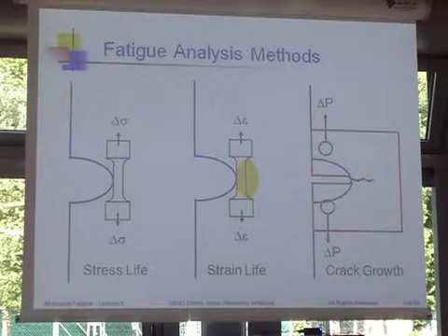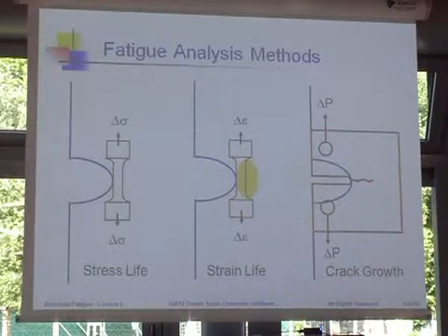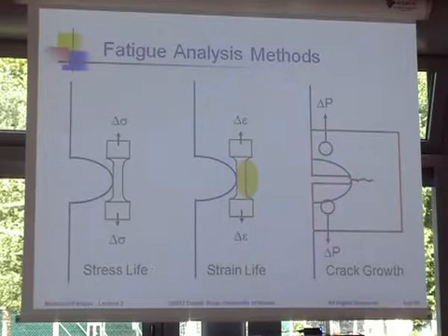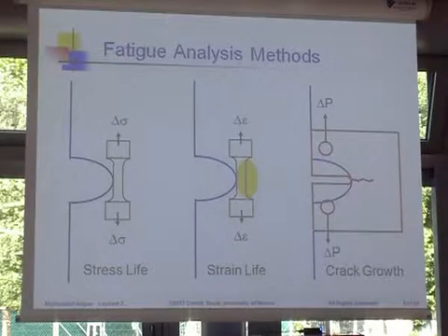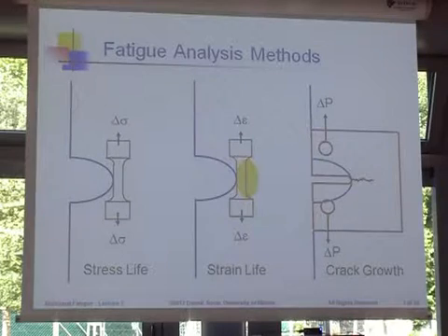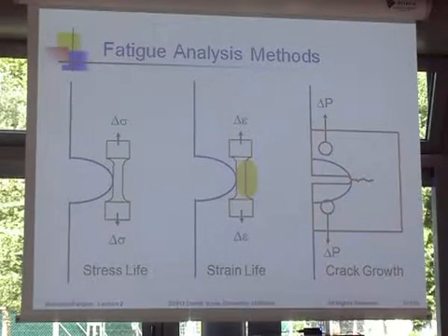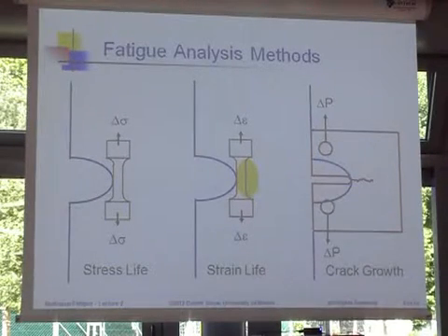Or finally, I could think about that a crack forms in the structure, and I just have to deal with crack growth, and so I just draw a little schematic of a compact tension specimen. And depending on where you go to school or where you go to work, your view of fatigue generally falls into one of these three different classifications. And so before I actually go into the stress-based models, I'd like to take a few minutes and just talk about the three global approaches first, right? How do I choose to solve the problem?